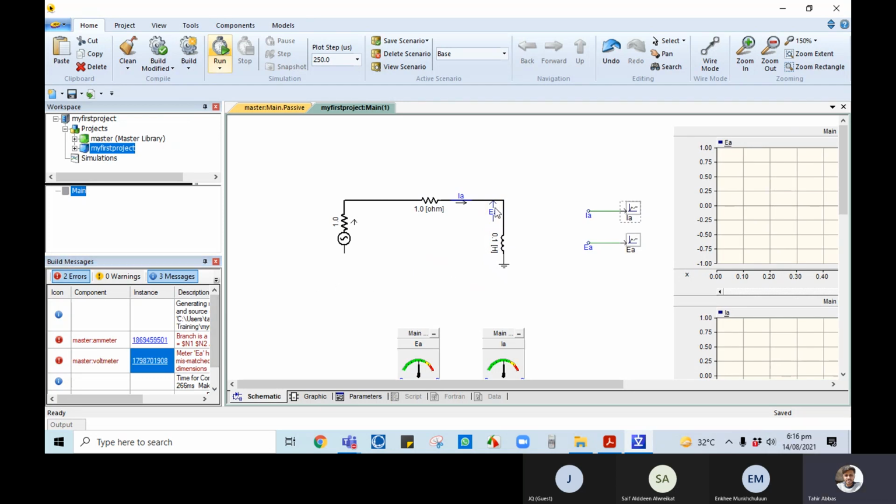So in this way, we need to measure in the correct fashion. Delete this wire and first place this one. Then click on wire, go up to this and then press escape. We know it is in series. Then it is in wire, and then press escape.